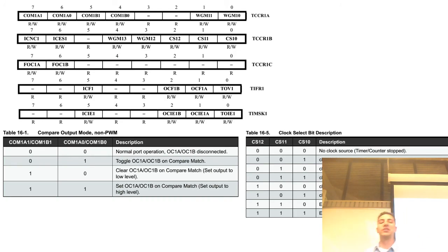Let's talk about what we can do to configure this stuff, okay? The configurations all follow the same basic patterns. What does that mask register do again? Oh, geez, nobody's answering, so I just assume that it hasn't sunk in yet. The mask register tells which interrupts can fire. Oh, look, there's the mask register. So what interrupts are possible?